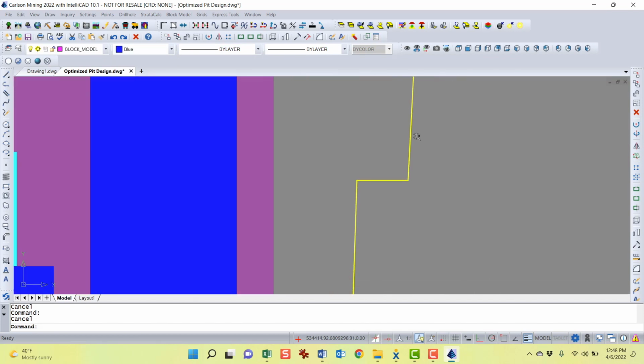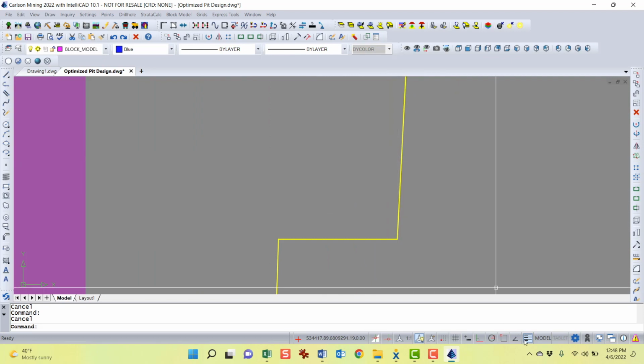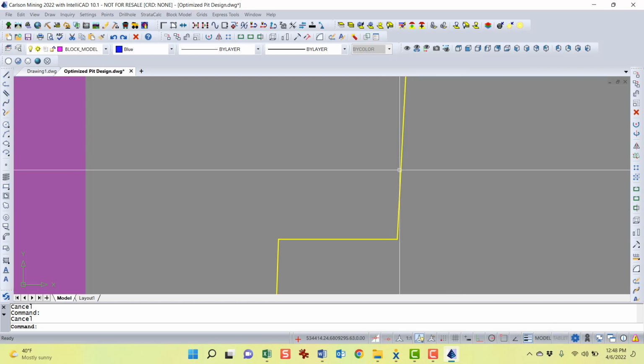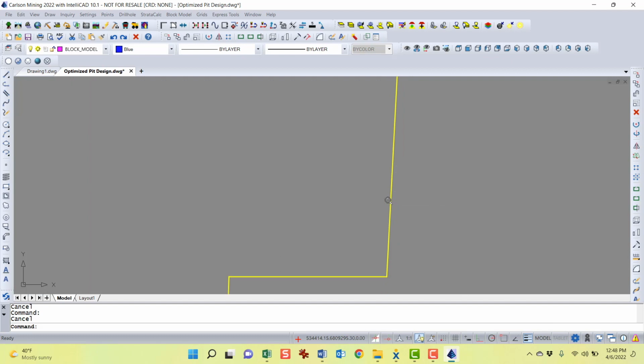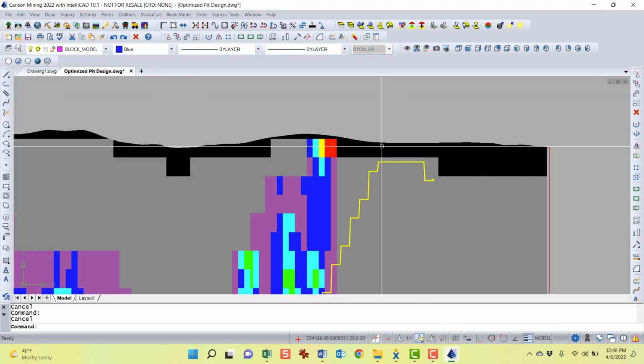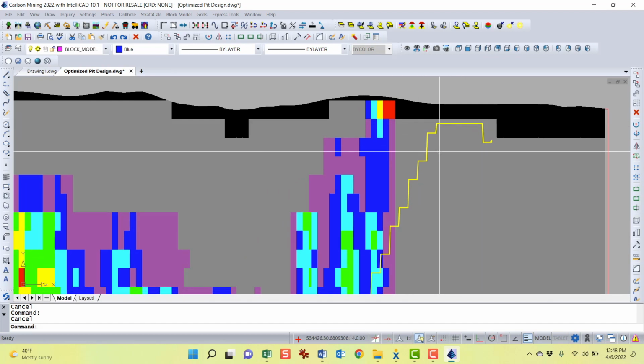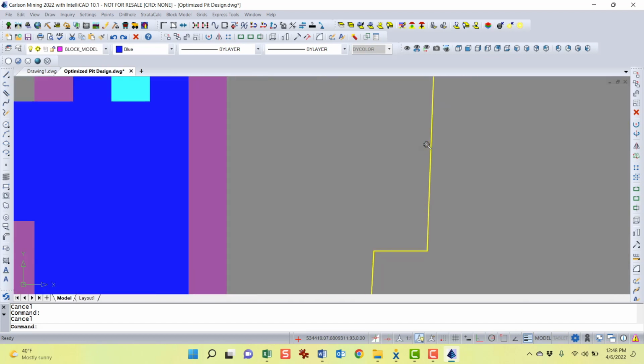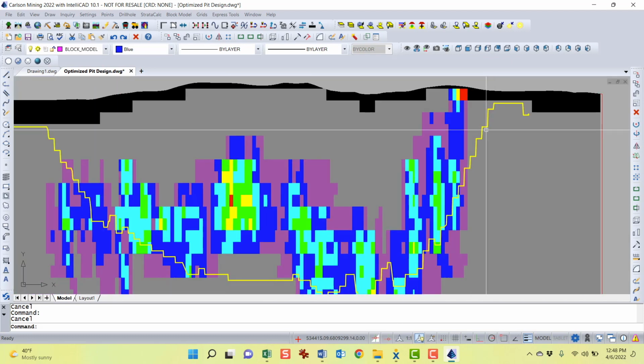And I also have line weight turned on. We didn't really discuss line weight, but if you're an AutoCAD novice, there's something that is down below these line weight displays. You can give a line weight, but it doesn't change. So if I zoom in or zoom out, that line stays the same. Whereas if you had an AutoCAD thickness, maybe of 5 feet, and you zoom in, it'll get thicker and thinner as you zoom. But the line weight is good for just emphasizing polylines.